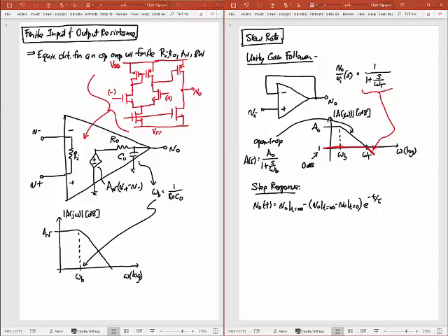Right? So it's going to have some exponential quality to it, or a 1 minus that exponential quality to it. And I can then break this down to V0 at t equals infinity times 1 minus e to the minus t over tau. Okay, that ends up being my transfer function.